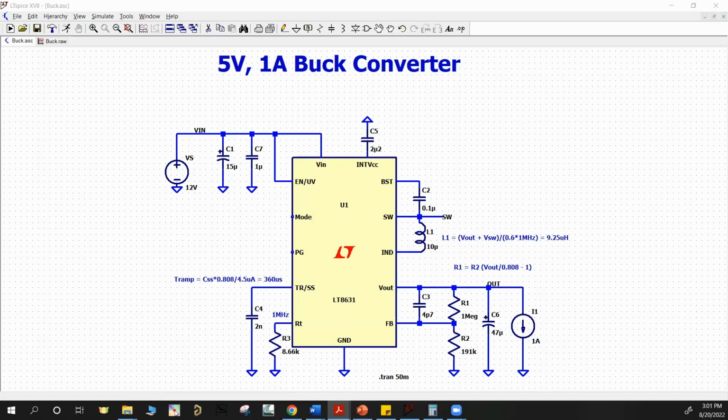You could select between burst mode operation or pulse skipping operation. Burst mode operation is usually used in order to optimize performance of the switcher at small loads. What that means is if we ground this particular pin, it indicates that this chip is operating under burst mode operation, where at low load, when you have no load or milliamps of load, this switcher IC ensures that it consumes the absolute minimum current.